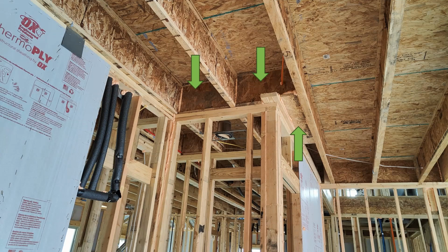But a band joist, not created by framing, must exist directly over the garage wall to the conditioned subfloors above. In this instance, there's a door leading inside the house that juts out, so they've created the band joist as it goes horizontally across the screen, and then you've got the vertical TJIs going through there. Even the underside of this, the conditioned floor cavity in that area, was also blocked underneath and then sealed on both sides.